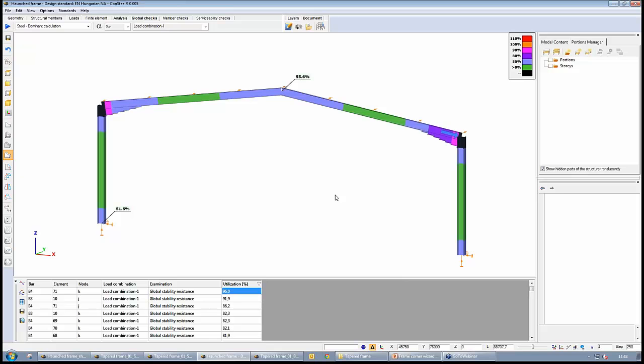And this shear area is, as I mentioned, checked in the connection design, because one of the components which are evaluated in this type of beam to column connections is the shear in the column web, taking into account the possible stiffeners, shear stiffeners, or just upper lower stiffeners.